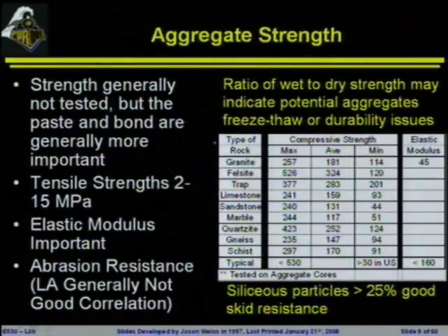Aggregate strength, generally we do not test the strength of the aggregate. So if you went to all the producers in the state of Indiana and you asked them what's the strength of their limestone, they would probably look at you like you have no idea what it is you're asking, because they've never been asked that question before, because they don't test it on a regular basis. Generally, we don't test the strength of the aggregate, but I've given you some general properties in the table over to the right. Paste and bond properties are generally much more important.